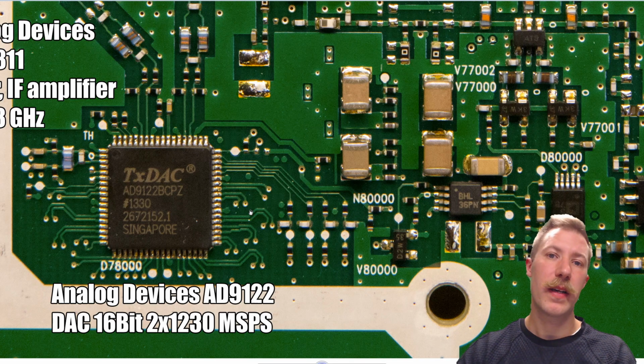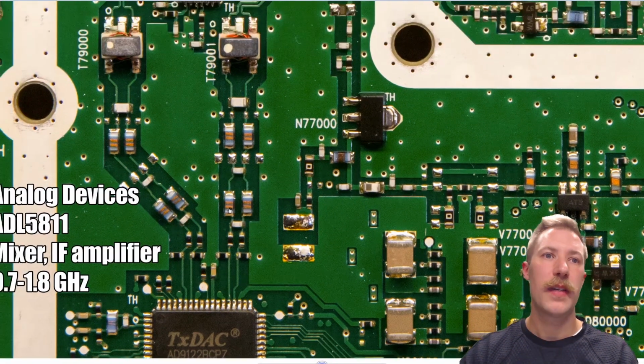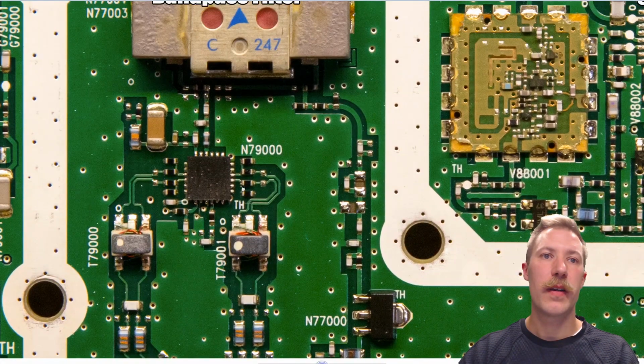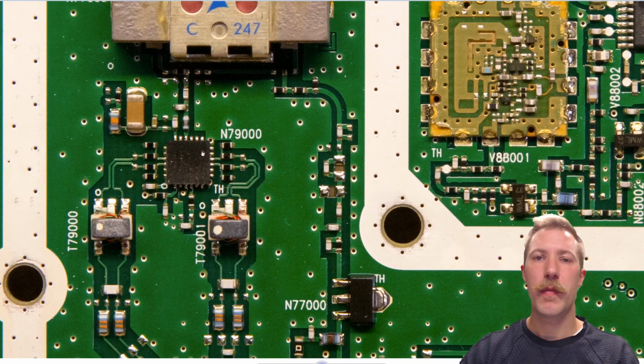It has a whopping 1230 megasamples per second conversion on dual lines. So we can see a lot of data points for the digital input connecting down here at the bottom, and we have the two dual line outputs. As we can see, impedance matching, some small filtering goes up here, and we have maybe a low noise amplifier. It does not have any part codes that I could read out even under my microscope.